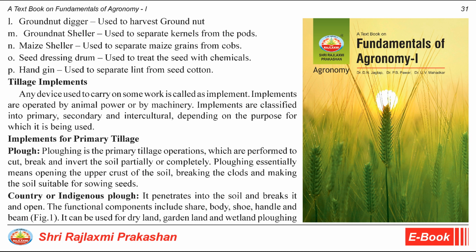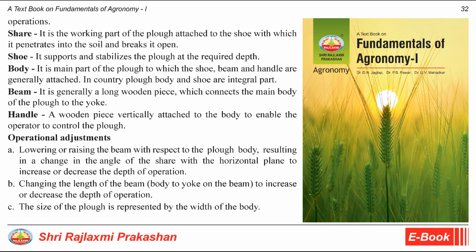It penetrates into the soil and breaks it open. The functional components include share, body, shoe, handle, and beam. Figure 2.1. It can be used for dry land, garden land, and wetland plowing operations. Share. It is the working part of the plow attached to the shoe with which it penetrates into the soil and breaks it open. Shoe.